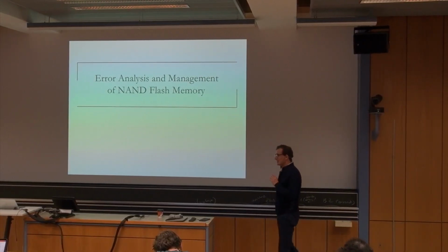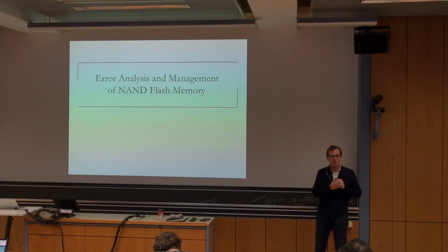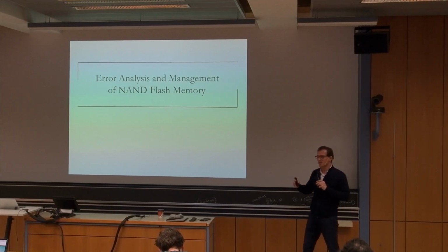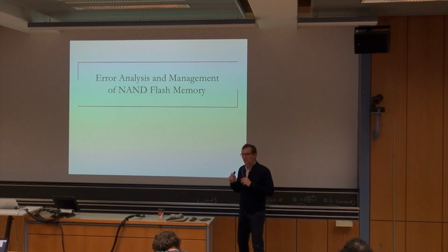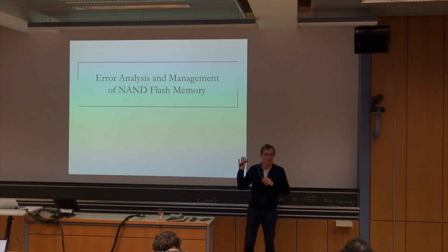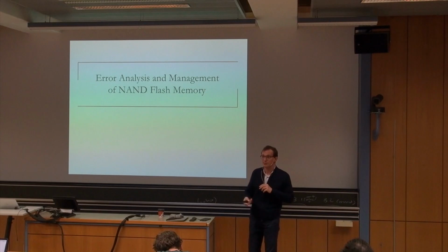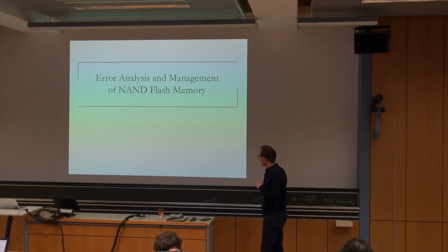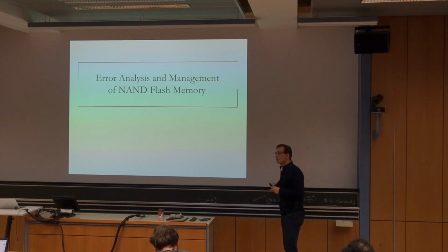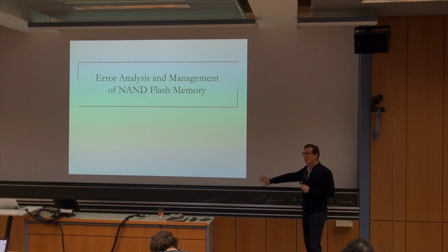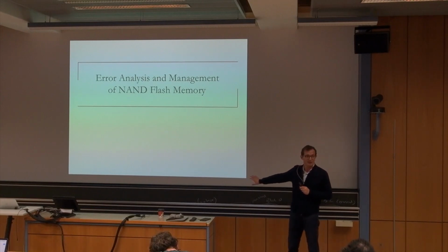By the way, I talk about erases, but these erases take a huge amount of time. They take 10 to 100 times longer than a read. So scheduling is another issue that we're not going to talk about, for example. How do you schedule these requests? Because you have read requests, you have erase requests, you have refresh requests, as we will talk about. How do you schedule all of these requests to flash memory becomes interesting. Ideally, you would like these erases to happen in the background. That's what these controllers try to do.